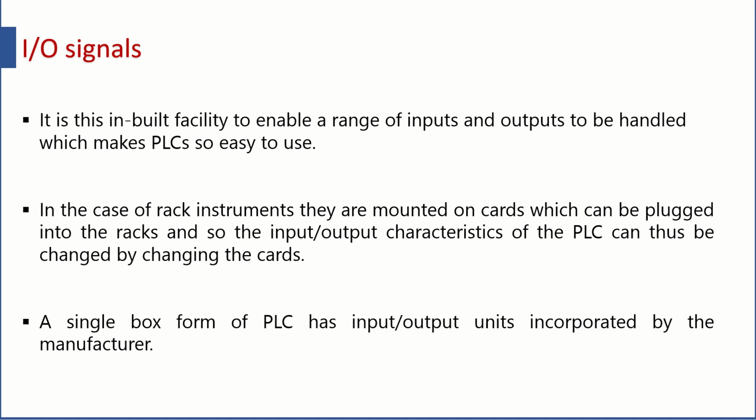If you know that your signal is lying somewhere between 3 volt to 10 volt, that signal cannot directly be connected or interfaced to the Arduino, because the Arduino will be damaged if a signal of more than 5 volt is given to some of its inputs. Now this is not the case with a PLC. PLCs are already built in such a manner that they can handle a wide range of input and output. Definitely that depends on the particular model of the PLC and the specification given by the manufacturer for that particular model. That you need to be ensured.